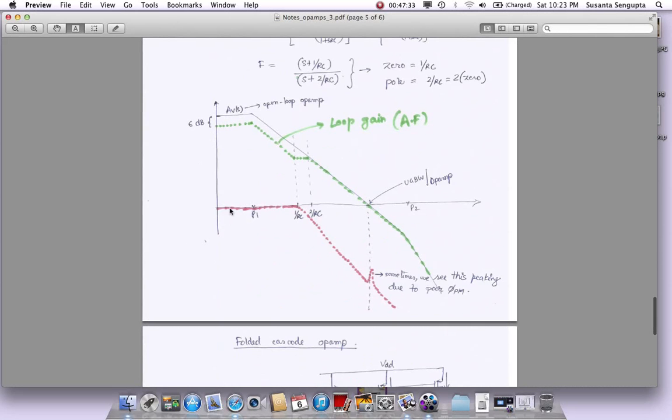So coming back here, the closed loop response. You have the plot coming in, the RC pole, you see it starts rolling down as a single pole response, and then when you hit the unity gain bandwidth, and this is something you will not see till you simulate, you will start seeing that there is a peaking that happens and goes down. This peaking is sometimes what you will see in the simulator around unity gain bandwidth. You may not care about it that far out because you already caused the pole which is 10 times lower. Whatever this frequency is, this is roughly 10 times more frequency.